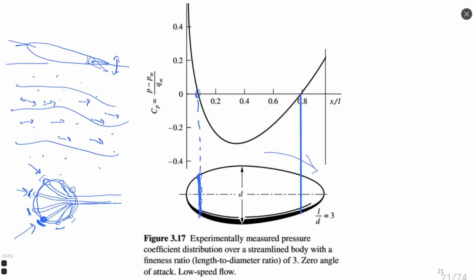A disadvantage of such a sensor can be only the space which they occupy, because when you have several points, several dots, you need space to put them inside the sphere, and it can be bigger than just a Pitot tube, right? Can be bigger. The smallest one I saw of such type of sensor was on the order of 3-5 millimeters. So such a sensor can be really small and measure with good accuracy direction and the value of the velocity.